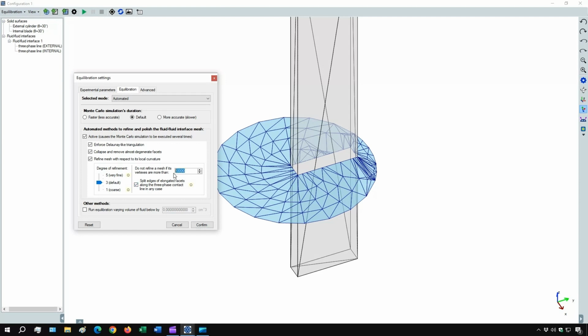In this way, the mesh will keep its refinement not too high, and this will prevent the simulation from becoming too slow. In addition, we enable the option to keep the mesh boundaries sufficiently refined to avoid problems due to the solid surface concavity.